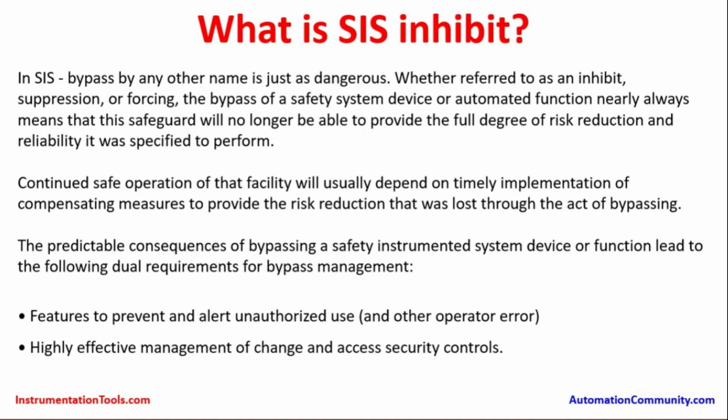Under the process, as per the operation sequence and operation phenomena, the pressure may get high sometimes. So if it is not controlled uniformly, there could be a chance of pressure getting high and leading to a hazardous event. But to take care of the maintenance of the transmitter, we are just forcing the logic as if the process is healthy, and then taking care of the maintenance. So the maintenance personnel need to complete the job quickly and then return the instrument to the normal operating condition.